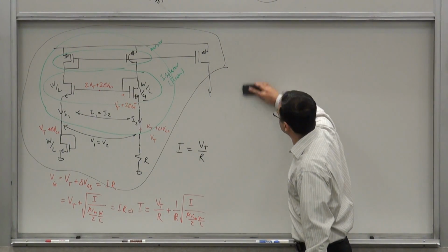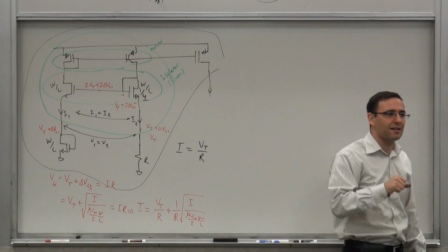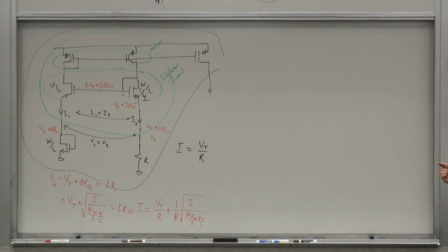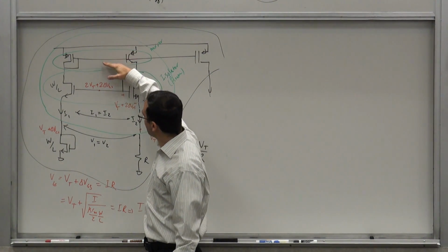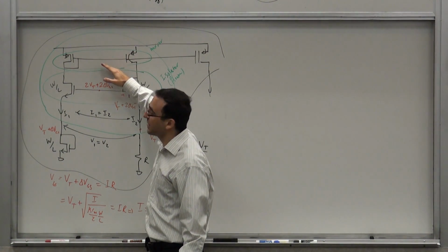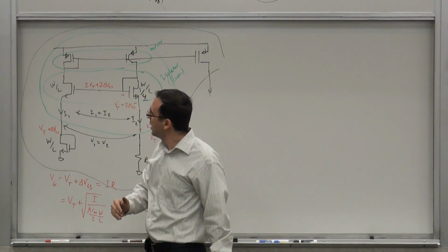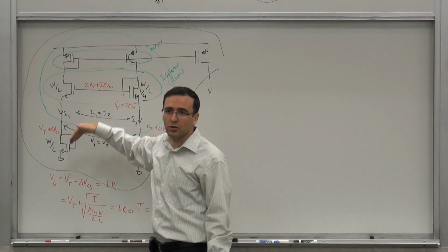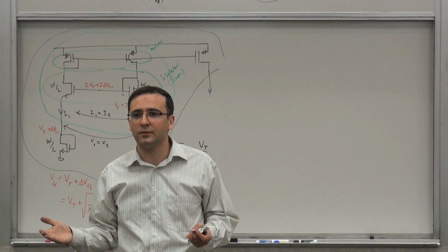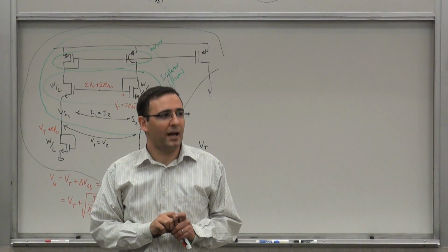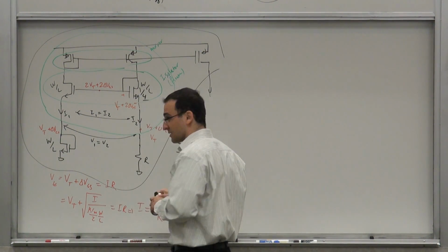So, anyway, is this good? Well, it doesn't show a direct dependence on the supply. Of course, if you take channel length modulation into account, then you have some dependence on supply. It has significantly been reduced, and you can even reduce it more by making them Cascode. So you took care of the supply dependence to first order, but how about other things like temperature and process?